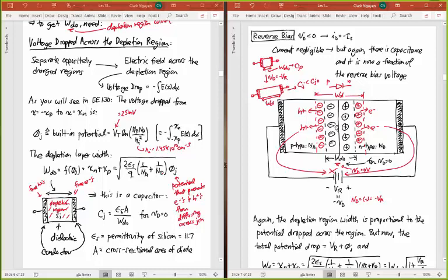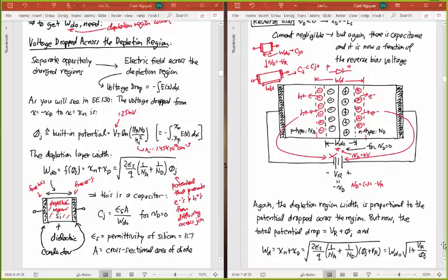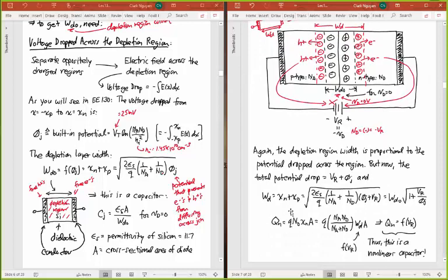And so what this is telling you is that I'm changing the voltage across this capacitor, and changing the voltage across this capacitor changes the value of the capacitor, because it changes the distance between those plates. And so I now have a capacitor that depends on voltage, which means it is no longer a linear capacitor, it is a nonlinear capacitor. And so I can write that in terms of equations, which I've done in advance right here. So I've sort of written down what I said.